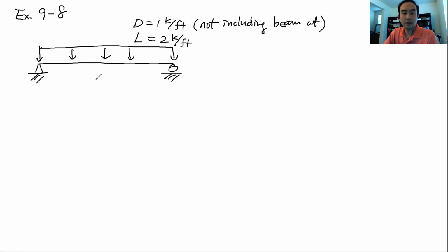And the entire span of this beam is 20 feet. And there's one specific piece of information about the lateral bracing. It says that it has lateral bracing provided for its compression flange, which will prevent the lateral torsional buckling, right? Only at its ends. So we do have lateral supports, but not along the entire length of the beam. We only have the lateral bracing at each support.